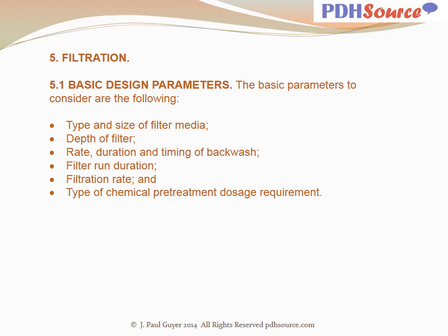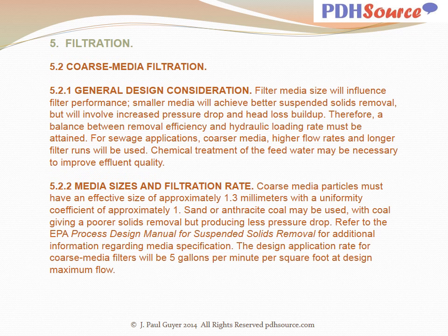Filtration is the next advanced wastewater treatment methodology that we will discuss. The basic design parameters to consider are the following: type and size of filter media, depth of filter, rate, duration, and timing of backwash, filter run duration, filtration rate, and type of chemical pretreatment dosage required.